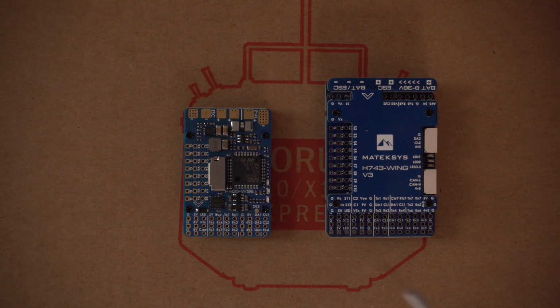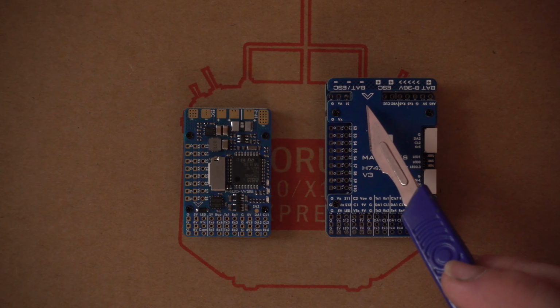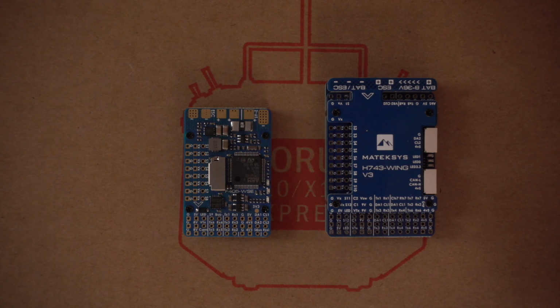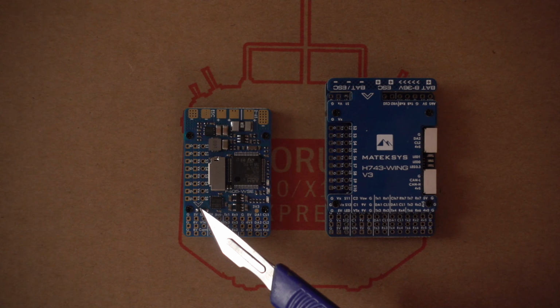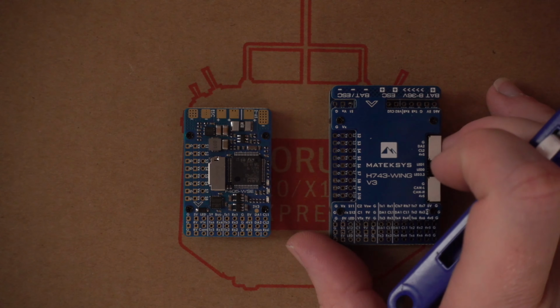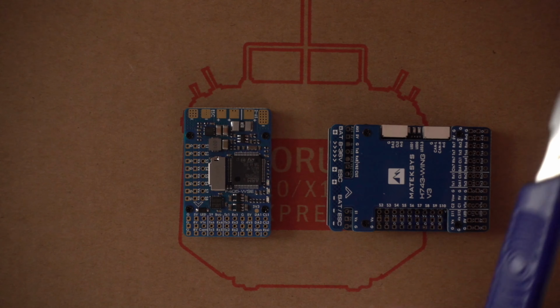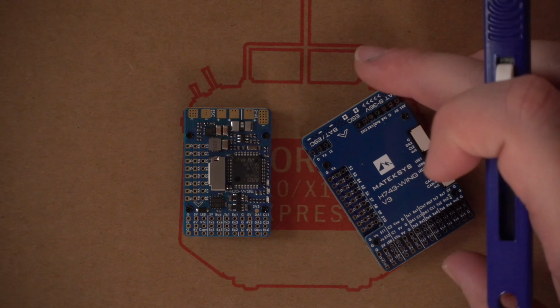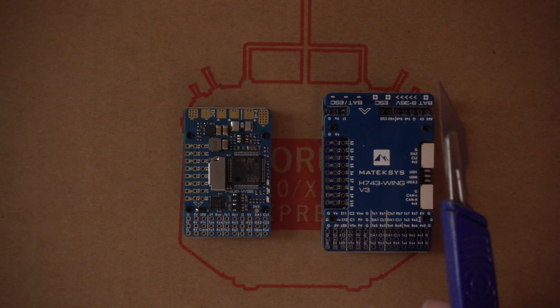Right, so one of the first things that you might see on these flight controllers are these arrows. What they're basically stating is the forward direction of the flight controller by default. You can actually change the orientation in the model if you wish, but if you set it up with this arrow facing towards the front of the plane, it will all work straight away. We can rotate it if we choose, and there's a command in iNav to actually say that this is the front now. But I don't really want to overcomplicate things too much at this stage,